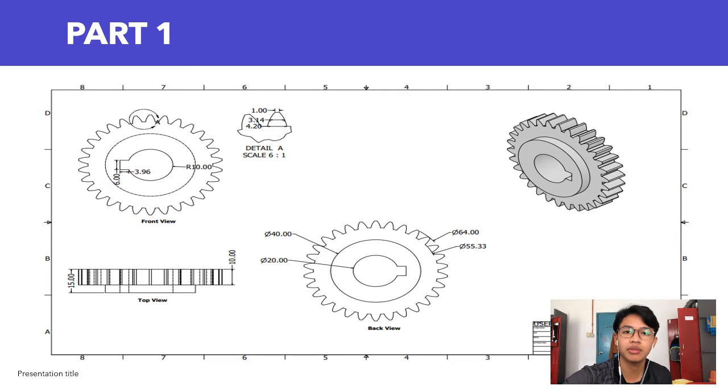Okay, so the first step is to make a pitch circle with a 60mm diameter, an addendum circle diameter of 64mm, and a dedendum circle diameter of 55.33mm. The next step is to create an arc between the addendum and dedendum circles and use a coincident constraint, then mirror it with respect to the y-axis and set the base of the tooth dimension to 4.2mm.